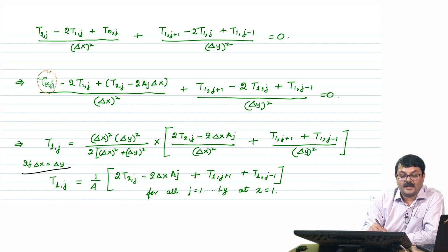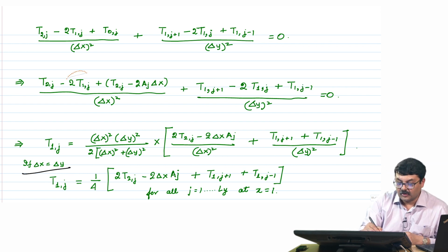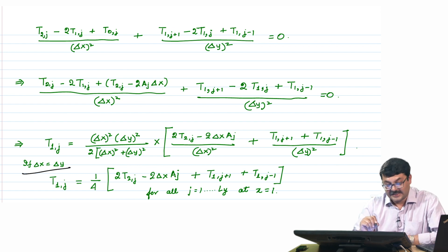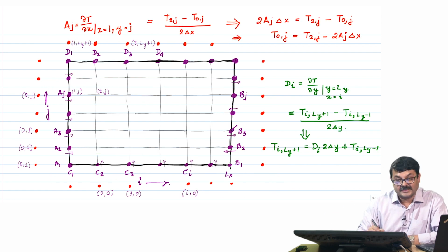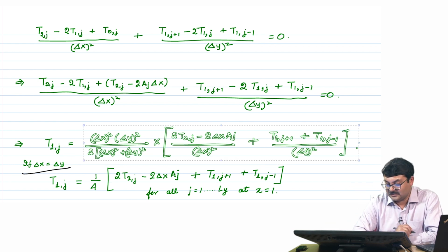But at least at your 0th iteration and your 1st and 2nd and whatever nth iteration, for each case you have the values of all these quantities, right. So, now you solve for basically T 1 j along the boundaries. T 1 j is the temperature at this point and this point for different values of j along the y axis, right. So, j is varying; for each value of j, you find out the temperature at the boundary, and the formula, by just doing some algebraic manipulation of this, you basically get this, right.